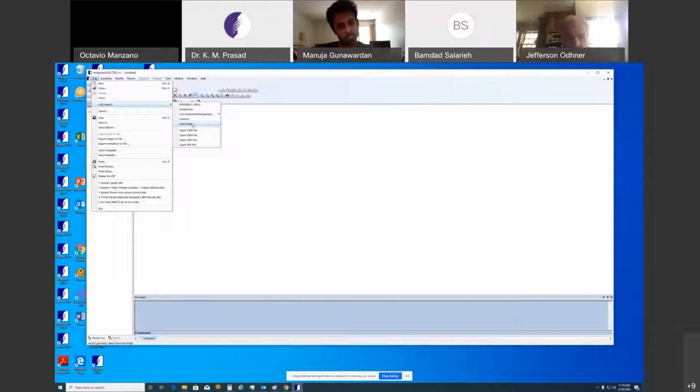These are five direct links, but suppose you have a different CAD program, what you can do is save the file in your CAD program in IGES or DXF or STEP format, and you can open the files in our program.